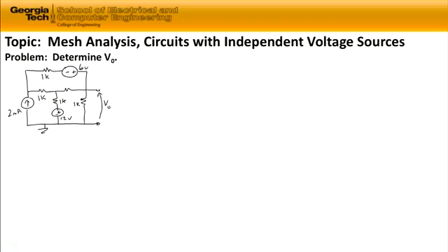The first thing that we know is that mesh analysis is performed using Kirchhoff's voltage law. So we're going to use Kirchhoff's voltage law. And after we realize that, our first step as far as circuit analysis will be to determine and assign loops so that we can sum up the voltages around the loops using Kirchhoff's voltage law.